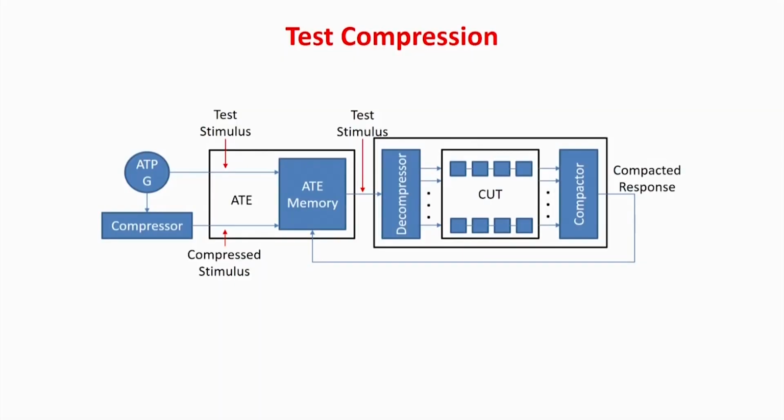Reducing the number of test patterns falls under ATPG generation, and in fact ATPG algorithms are well optimized so that they do not generate redundant test vectors; they generate mostly the minimal number of test patterns required to test all the faults. Describing it pictorially, this is your ATPG algorithm, which will generate the test stimulus, the minimum number of test patterns required to detect the faults. But it will have 0, 1, 0, x, x, x, x. ATPG is not bounding the number of bits.